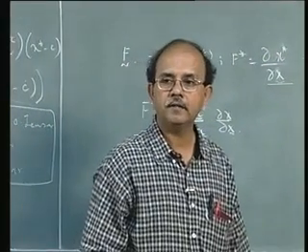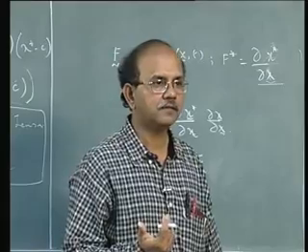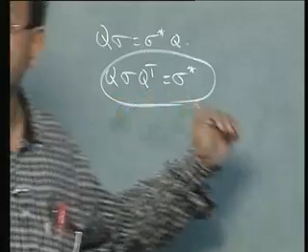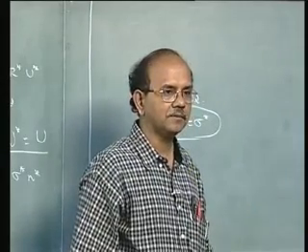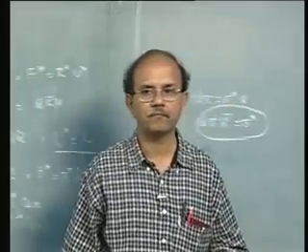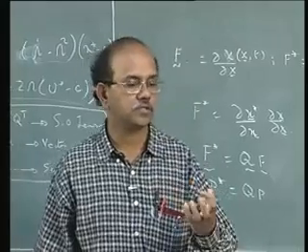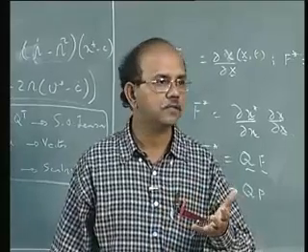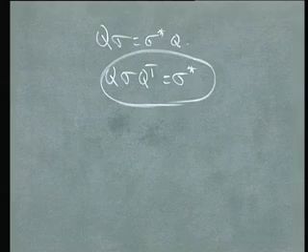So what does this say? This says that Cauchy stress is objective. So that's a very important thing. That's the reason why we use Cauchy stress in the constitutive equations without problems, because Cauchy stress is objective.